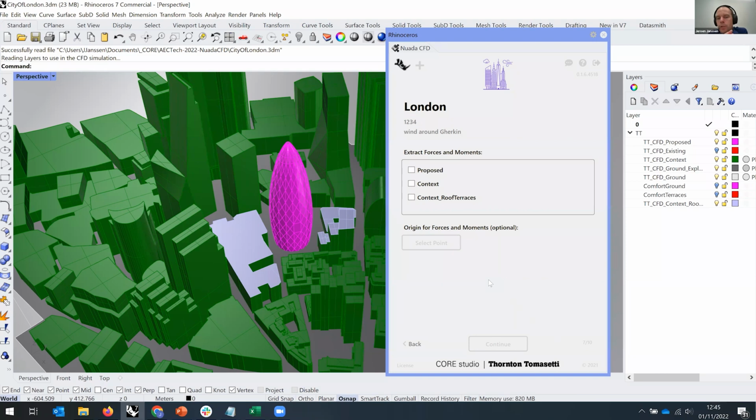I think what we do need to do, connecting back to the other question earlier, I think what we also want to put in is a wind speed as an input, right? What is it currently used for wind speed default? 10 meters per second at 10 meter height. And that's then a logarithmic profile, let's say. That's kind of the typical thing you would use for pedestrian comfort, because it multiplies up and down quite nicely because it's logarithmic. So you kind of log 10 cancels out a term in the division, basically.